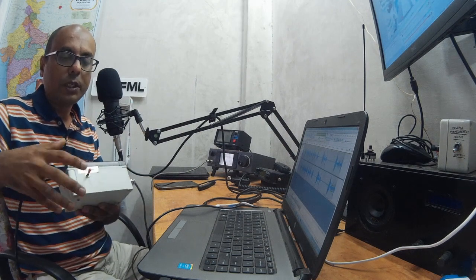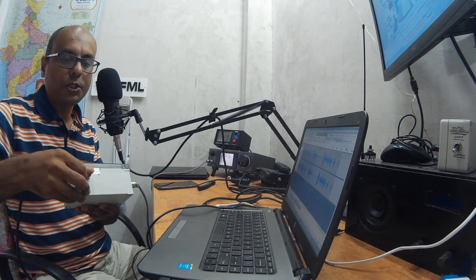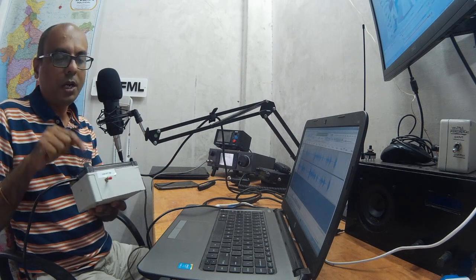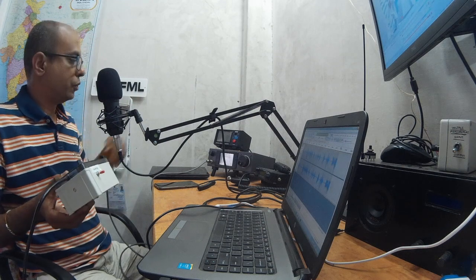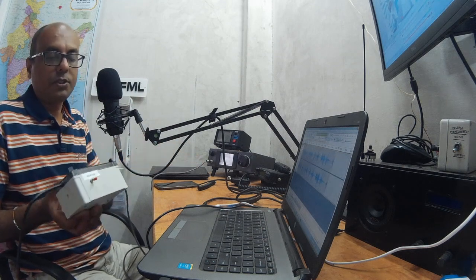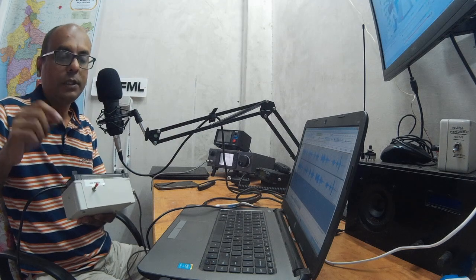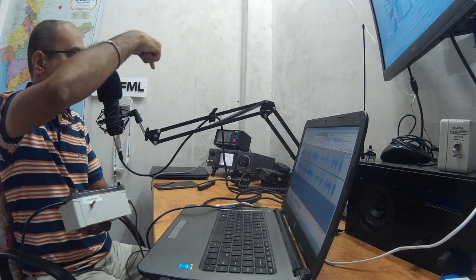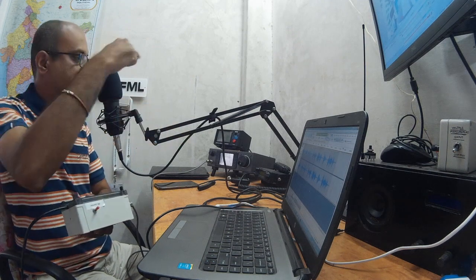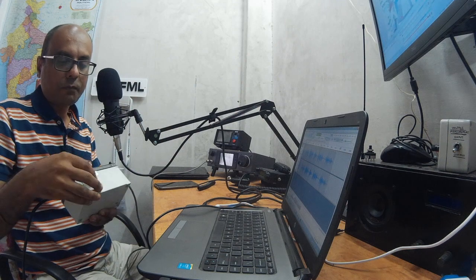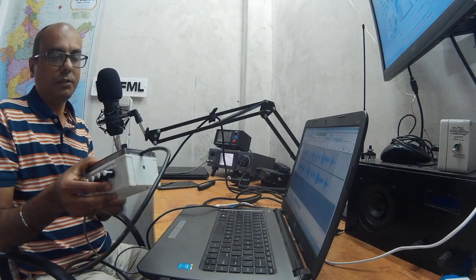This is the switch we talked about earlier. If I switch it on, the hardware will be used to trigger the PTT. If it is switched off, then you can connect another USB cable to the radio, and WSJT-X will trigger the PTT over CAT. I usually keep it on because I let the hardware trigger the PTT. That way I can use the sensitivity and the delay feature of this interface.